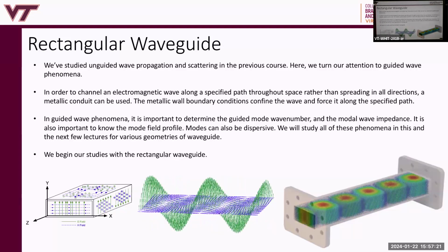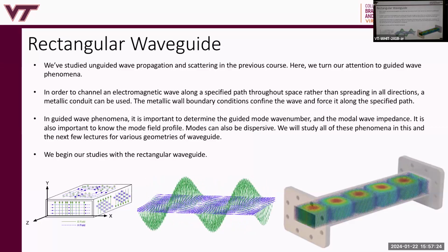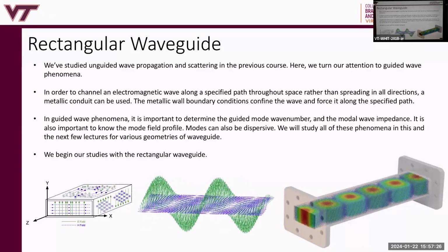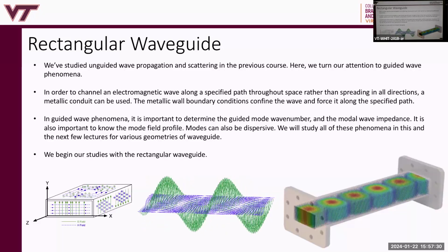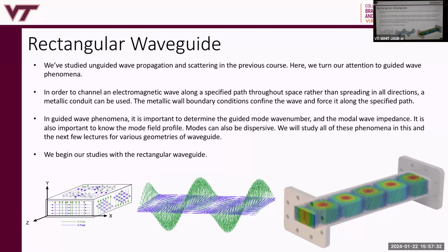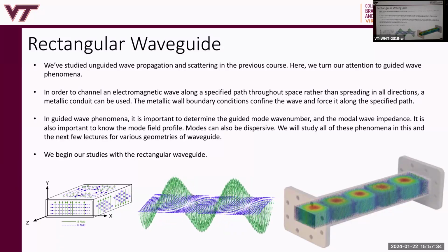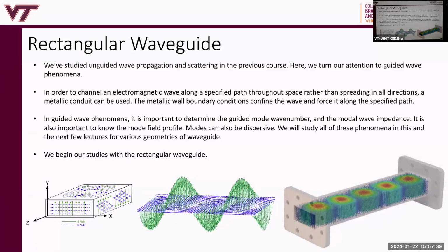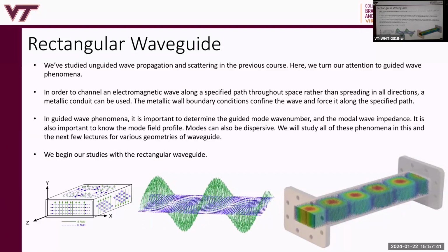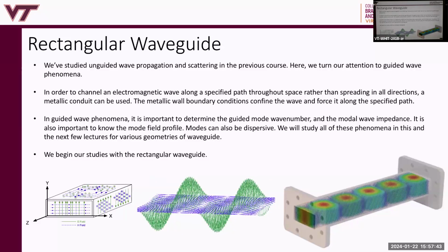So on the graph where we have the normalized frequency, what does it mean when we have the reactive impedance? When it's less than the cutoff frequency, you're below the cutoff frequency, with reactive impedance. If you were to calculate the Poynting vector in the direction of travel, you would find that there's no real power flow, right?